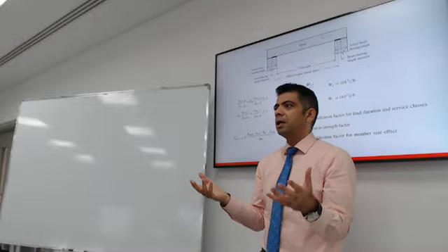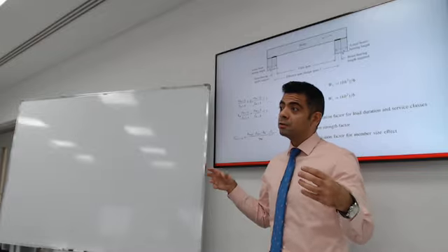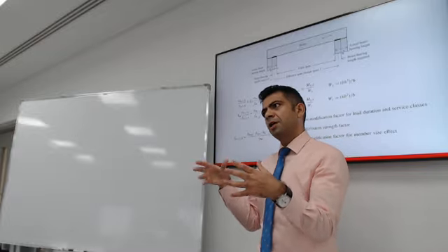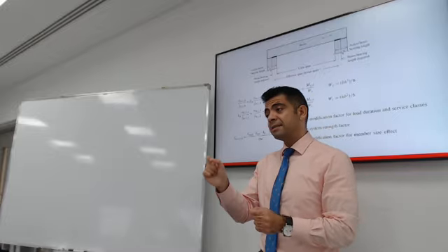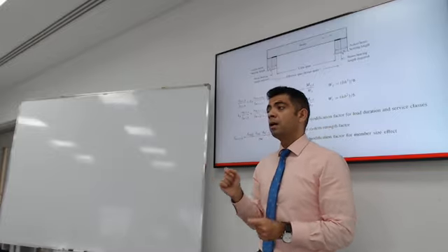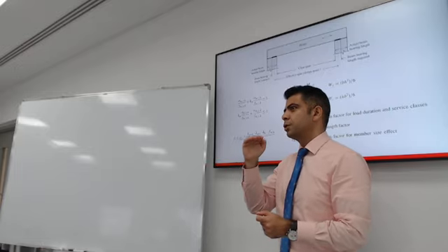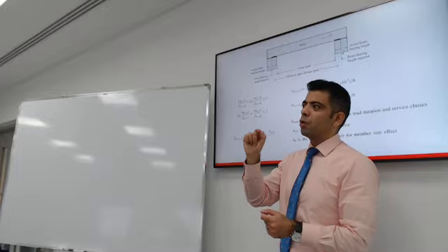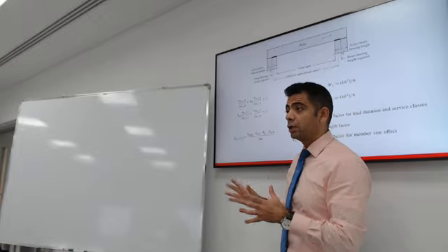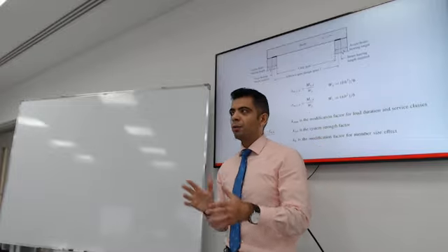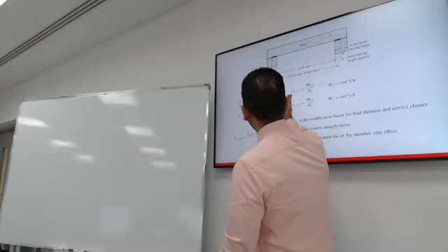It depends on the tree. But in the mill, in steel fabrication and hot rolled steel, it's a heavy industrial endeavor, and you can have quality assurance and quality control. And that's exactly why gamma M is 1 in steel, because we're so confident that we can consistently produce steel with yield that is 275 MPa. We don't need to reduce that much. With wood, we need to be careful with what we use. Excellent. All right.